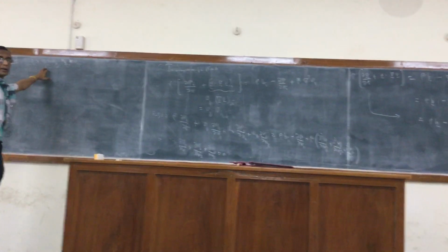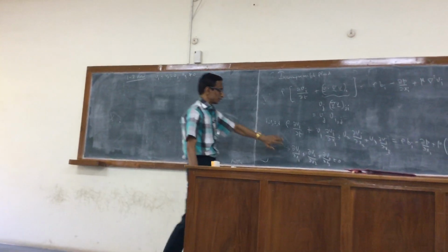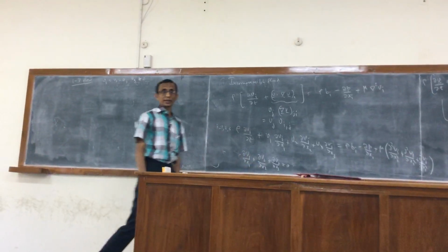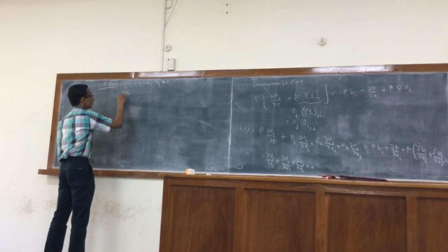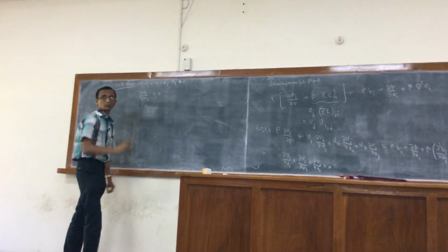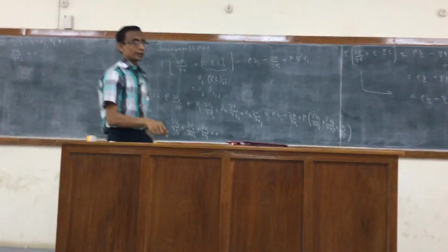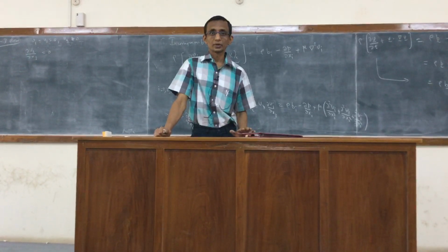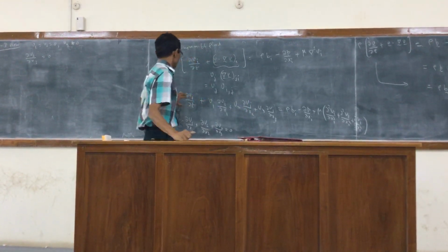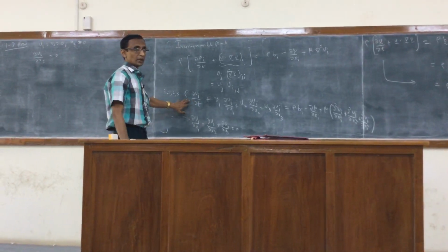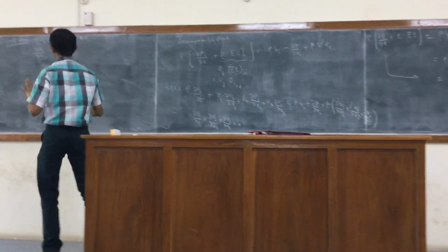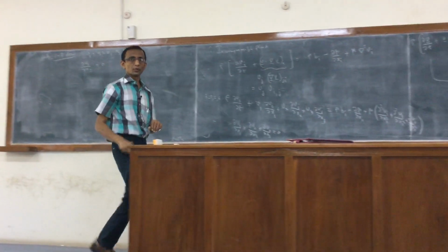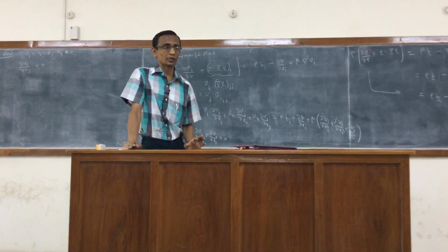So now what you see here is one-dimensional flow. First, if I apply the continuity equation to this particular case, we get that dV3 by dx3 equal to 0. That means V3 cannot depend on x3 for one-dimensional flow. Further simplification will arise if we also look at steady one-dimensional flow. We are really not going to consider unsteady flows for a large part of this course. We focus on steady flow.